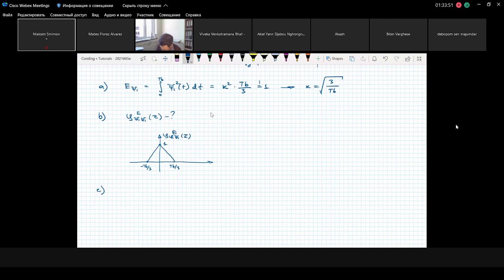So we say that this autocorrelation function for different delays we can find. And by the way, we also say that adjacent symbols are independent, and as a result, we can say that the autocorrelation function we can find if L equals 0 as the second moment, and the first moment squared if L is not equal to 0.